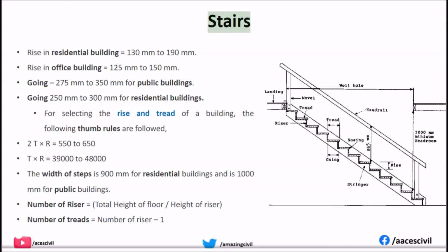Stairs. Rise in residential building equals 130 mm to 190 mm. Rise in office building equals 125 mm to 150 mm. Going 275 mm to 350 mm for public buildings. Going 250 mm to 300 mm for residential buildings.